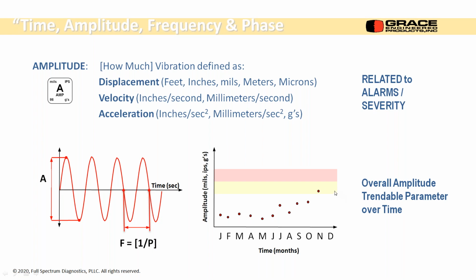So this might be an alarm level based on my chart of rules of thumb, 0.35 inches per second when it runs down here somewhere. I don't want to use 0.35 inches per second if I'm running at 0.1 all the time. I want to know how big and how fast it changes from 0.1 to 0.15 or 0.1 to 0.2. If I had this type of alarm on there too highly set, I might miss something like that.